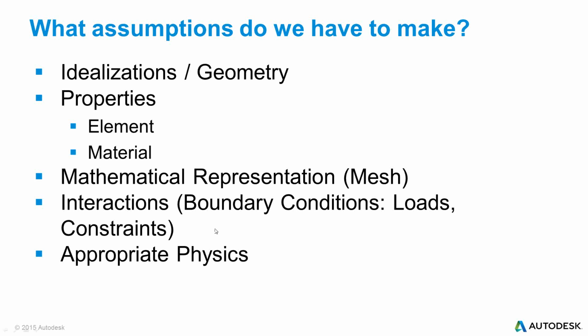The interactions with your environment, the boundary conditions, loads, constraints, are all, to a degree, assumptions. If I have a tire sitting on the ground, what is the pattern that the tire contacts the ground when it's loaded? I may be able to measure that and know exactly what it is, or I may make some assumption that it's a square, that it's an oval, or some other shape in order to come up with my analysis.